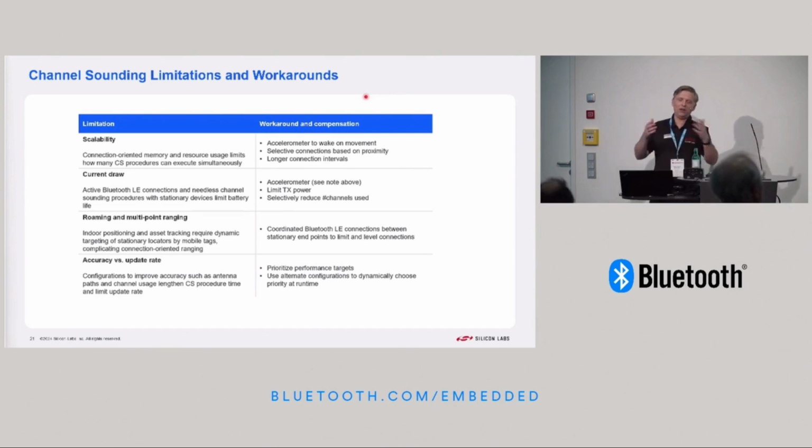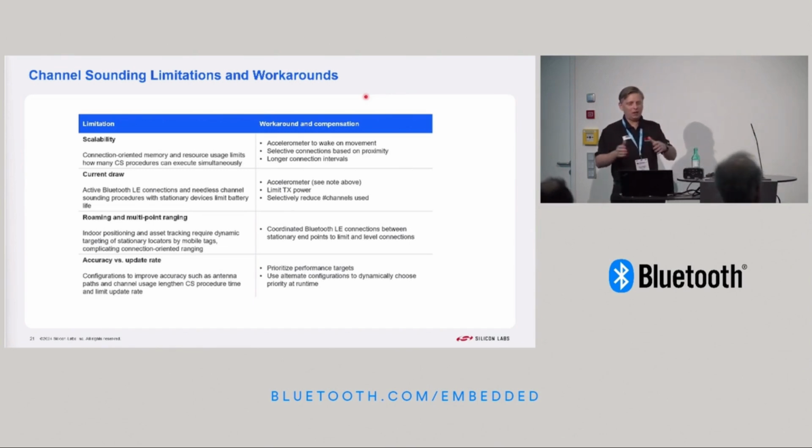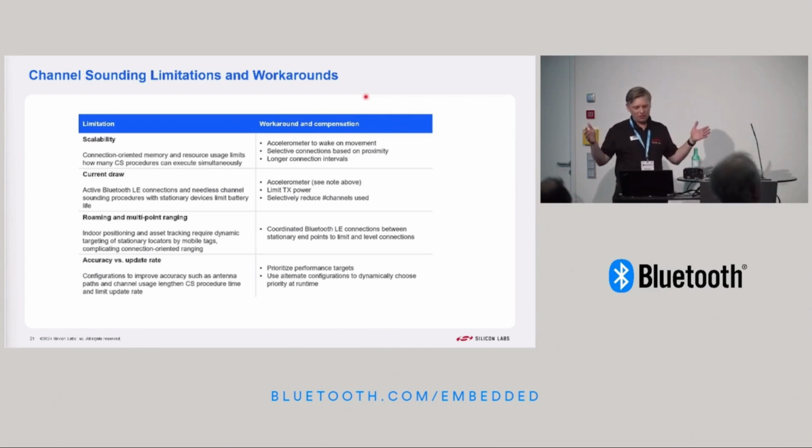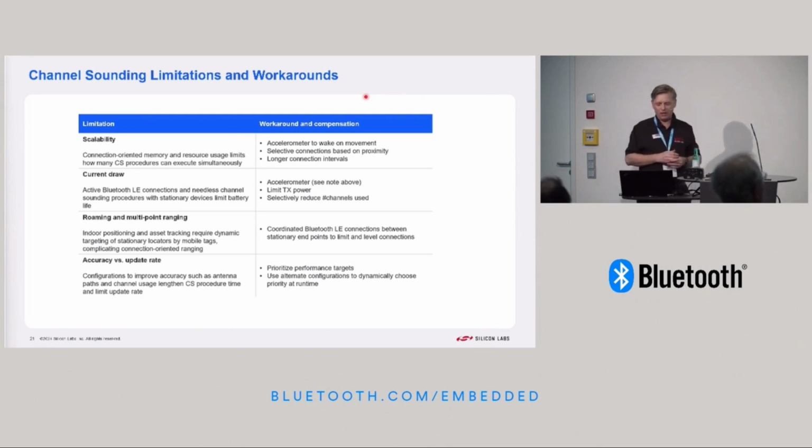And then another way to potentially improve the maximum number of devices that you can simultaneously scan is to use a longer connection interval. This helps with unsynchronized multiple devices that are communicating with each other.